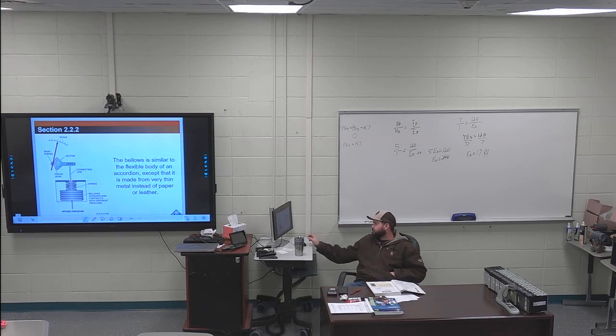So you can see your applied pressure comes in the bottom. This is a bellows. So this is like a metal bellows that expands and contracts based on pressure. Not a lot, just a little bit. So apply pressure here, it pushes against the spring, changes the connecting link, and then the gear changes the scale to whatever it is. Bellows type pressure sensing device.